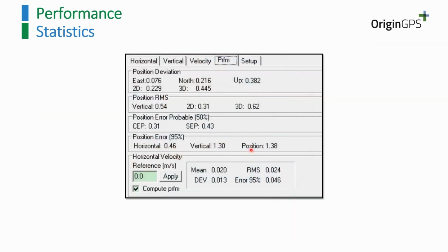If we are talking about statistics, it's not good enough to take only one measurement and see what your performance is. You should take at least 20 different measurements and then make statistical calculations. For example, here you can see what the accuracy is during 50% of the positions. We can see that the accuracy here is 0.3 meters. And there are more parameters that you should take care about, and it depends on your application.